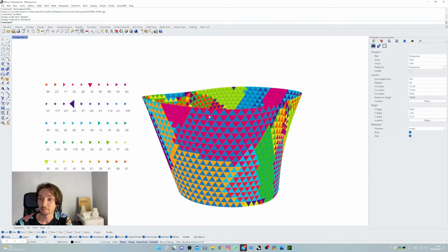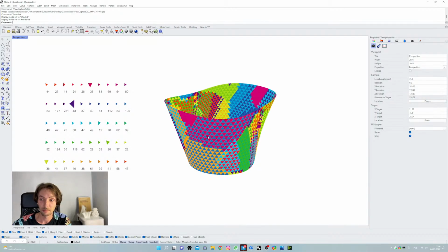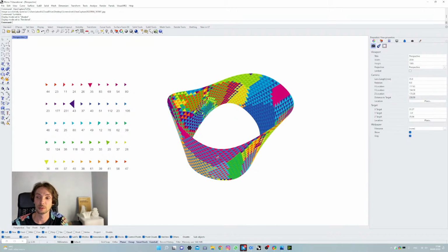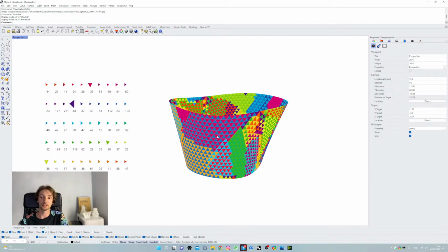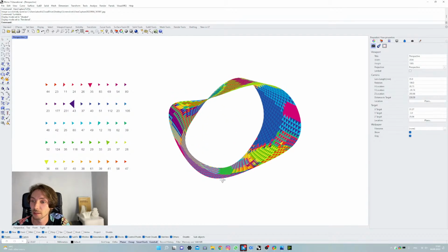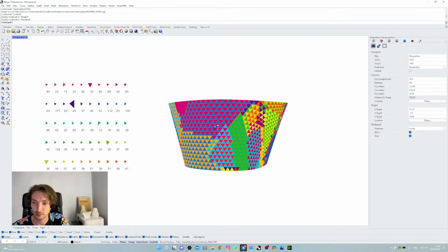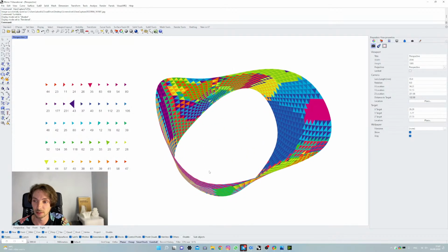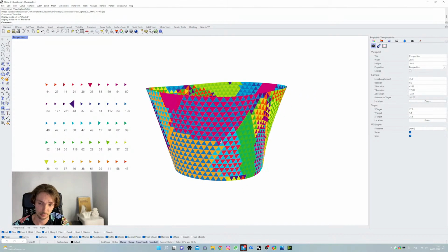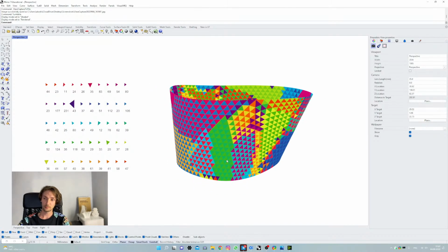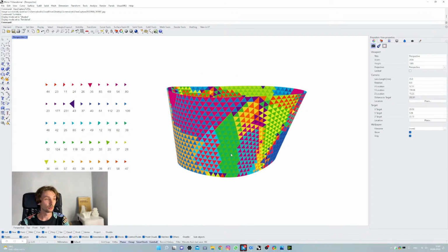And to be able to produce it, we will need to organize this facade, every triangle, in clusters, and unitize them. So let's say for each cluster we use just one single type of triangle, and that's it. In this way we'll be able to produce, let's say, 50 clusters, 50 groups of triangles, which will be much easier than producing 1 million individual pieces.